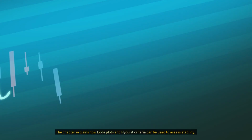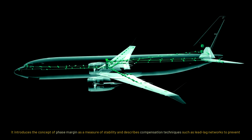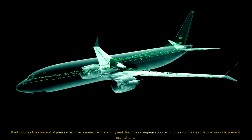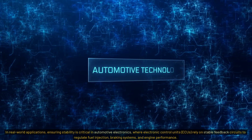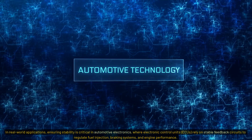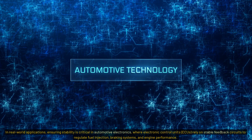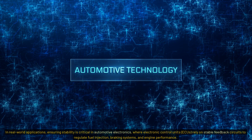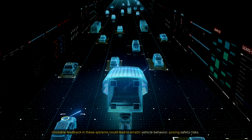If the loop gain becomes negative at high frequencies, the amplifier can oscillate. The chapter explains how Bode plots and Nyquist criteria can be used to assess stability. It introduces the concept of phase margin as a measure of stability and describes compensation techniques such as lead-lag networks to prevent oscillations. In real-world applications, ensuring stability is critical in automotive electronics, where electronic control units, ECUs, rely on stable feedback circuits to regulate fuel injection, braking systems, and engine performance. Unstable feedback in these systems could lead to erratic vehicle behavior, posing safety risks.